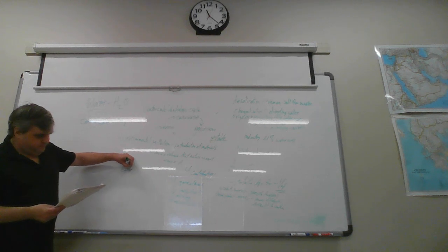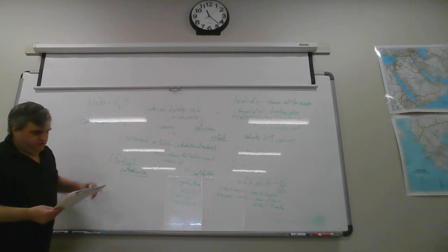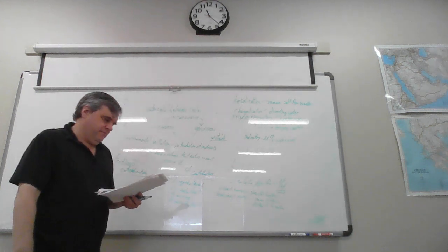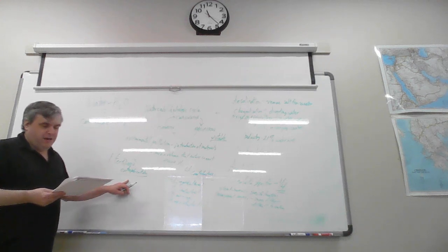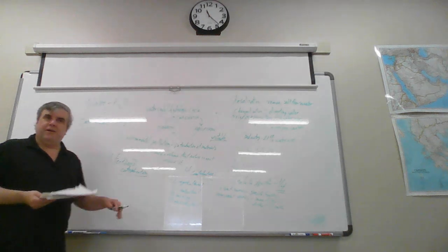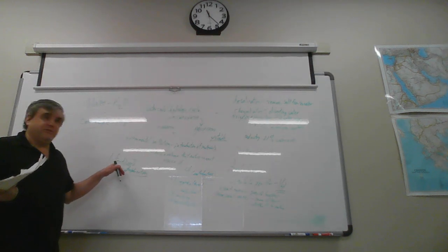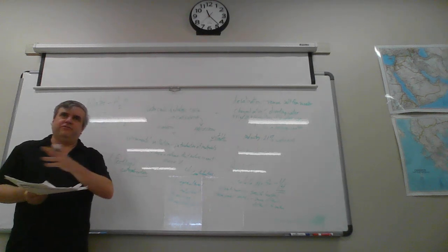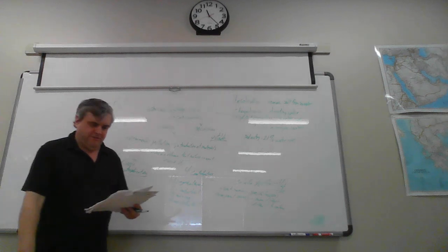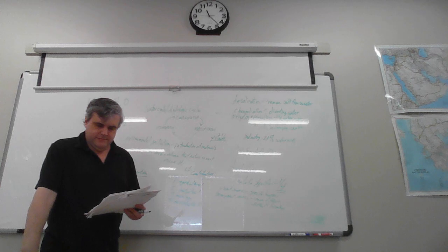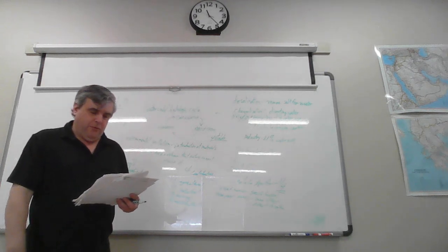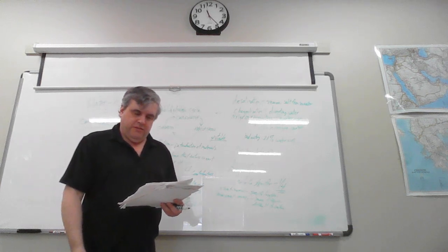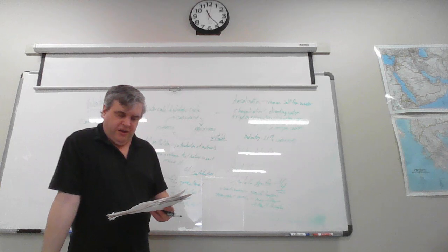So you get the idea of eutrophication. Eutrophication is the enrichment of waters by nutrients. Now, why is that a problem? Fertilizers increase algae and plant growth in water, which means more algae growing on the surface, blocking sunlight from getting into the pond. Organisms deeper in the water depend on this sunlight, and that causes them to die. And when they die and decompose, the level of dissolved oxygen in the water decreases, thus killing other fish and animals in the water.